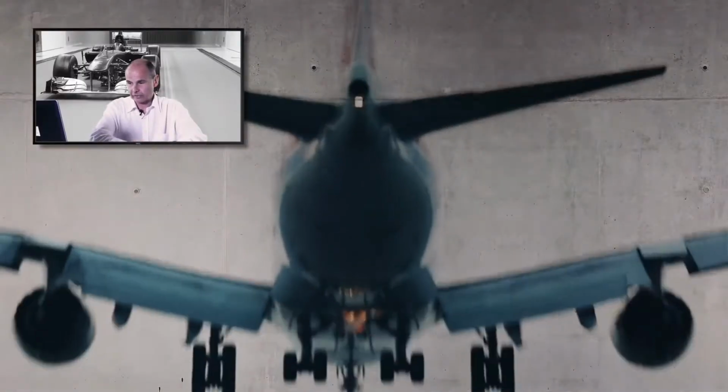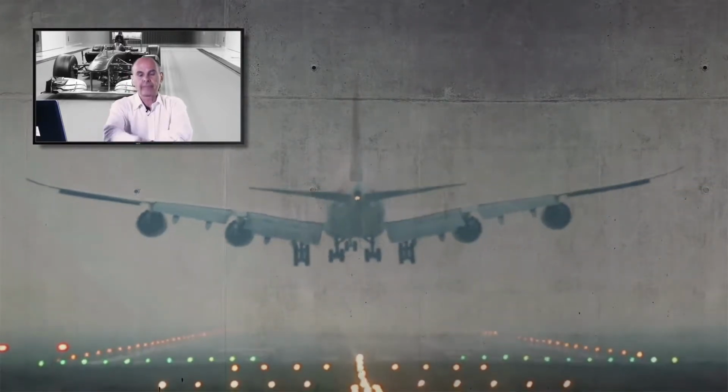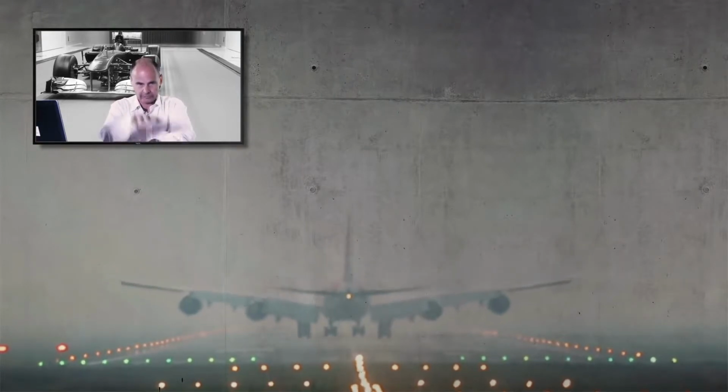So this technology has become very, very useful for other industries also, more extreme aircraft industries, to do their testing. So they would now be able to effectively land an aircraft on a belt in scale, of course. So that's moving ground technology, which has changed a lot. And one of the side effects of using this steel belted technology, because the friction is so low now, we no longer need cooling for our moving ground system. It's cooled by the air we pump underneath it.